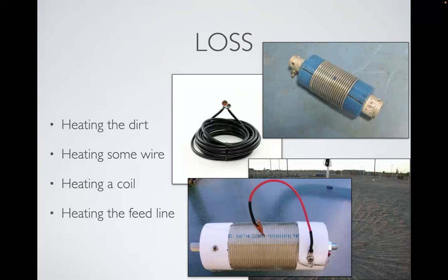The super antennas, anybody remember that? MP1 and stuff like that? That antenna has a shield over it. And so it's quite efficient because it covers up electrically that other half of the coil, and so it's not subject to these circulating currents. So I have arrangements where I either use a fixed coil or I can disconnect it so that we don't get that circulating current problem.